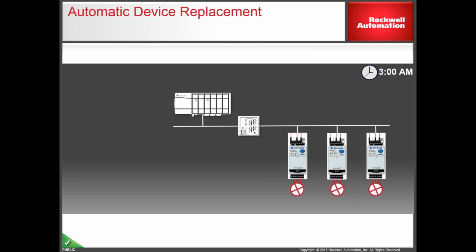Are multiple trip snapshots maintained in the E300? No, it just stores it for the last trip that occurred. Okay, so if it trips and the tech instantly resets it, the engineer has no idea why it tripped. It would retain the trip snapshot until the next one occurs. Until the next trip, okay. At that point, it's overwritten.